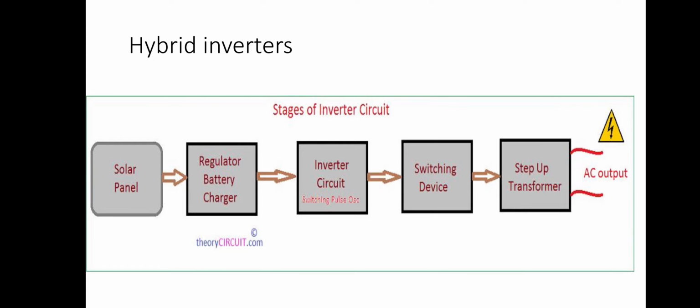So as I've said, the hybrid inverter, the only thing added is these first two chambers. There is this second chamber, sorry, the regulatory battery charger. Instead of buying a charge controller and mounting it on your wall, it's just attached into the inverter system, and it's called a hybrid inverter. It is not different from other inverters.